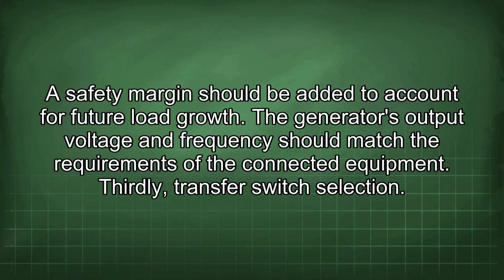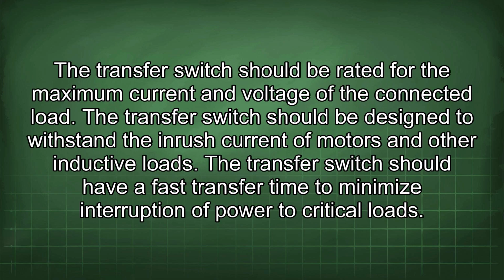Thirdly, transfer switch selection. The transfer switch should be rated for the maximum current and voltage of the connected load. The transfer switch should be designed to withstand the inrush current of motors and other inductive loads. The transfer switch should have a fast transfer time to minimize interruption of power to critical loads.